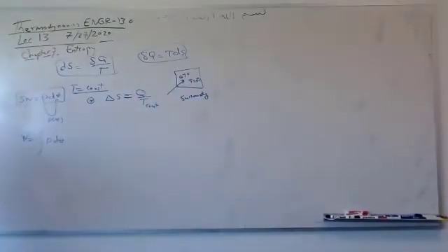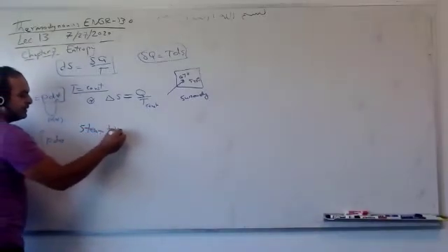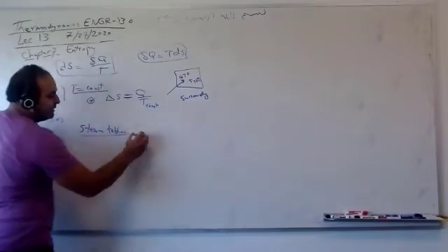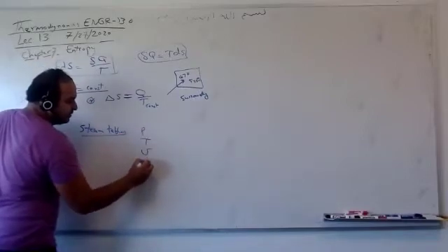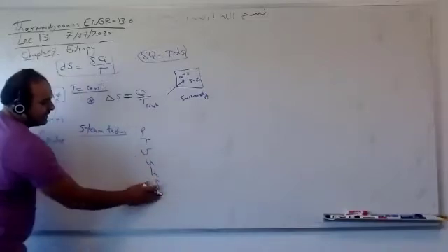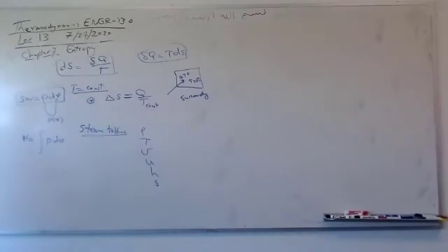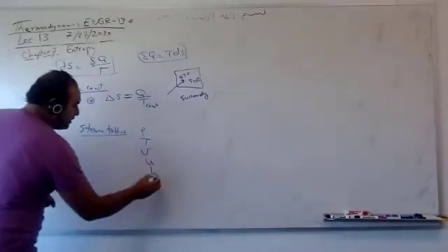Then we applied that also for steam tables. We learned that there is a new property. We have P, T, specific volume, specific internal energy, specific enthalpy, and specific entropy, small s. Again, the same units as internal energy and enthalpy: joule or kilojoule per kilogram Kelvin. Joule is correct, but the table is provided in kilojoule per kilogram Kelvin. This is a very important new property.